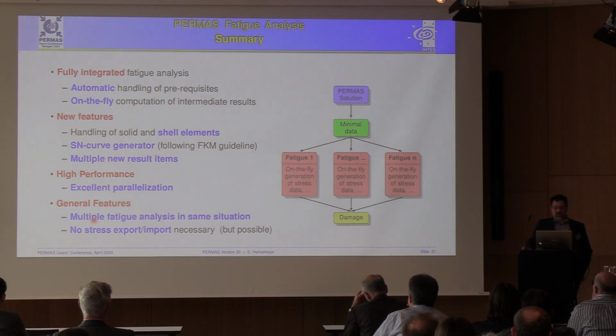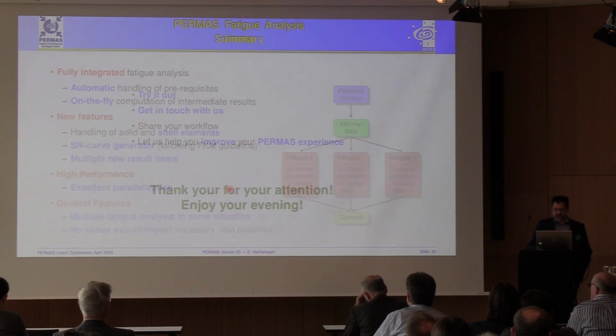And there is no need for a stress export or import. You can do this, but our recommendation would be to just store your displacements and recompute your stresses as needed if you're doing a fatigue analysis.